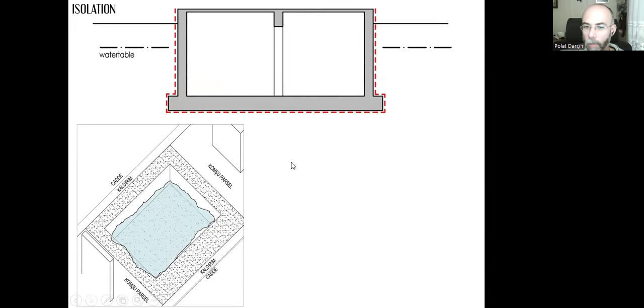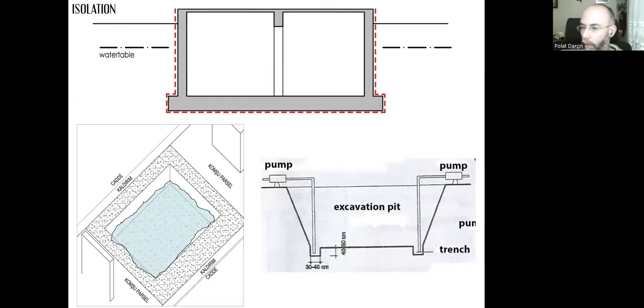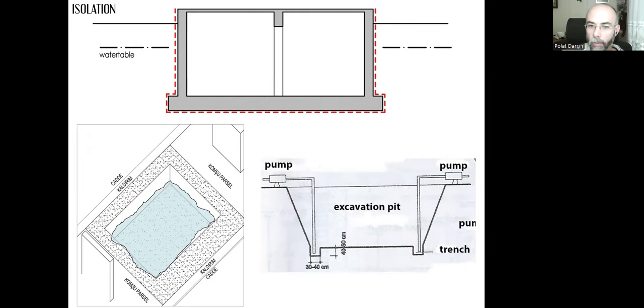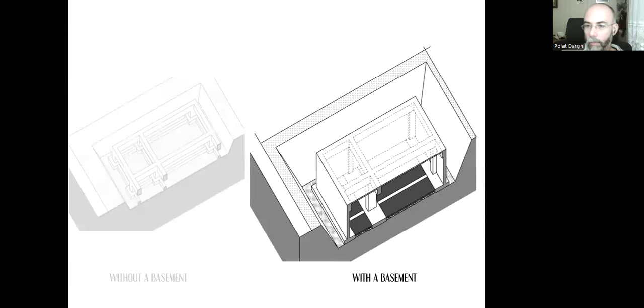And as we excavate, let's imagine that there is water. The water table is high like that. It fills with water. Then we can use some pumps to excavate that water. And this time we need a stronger waterproofing solution. It won't be appropriate for us to prefer waterproofing admixture anymore because with the waterproofing admixture, we will be protecting the reinforcement bars of these shear walls and the floor and the raft foundation.